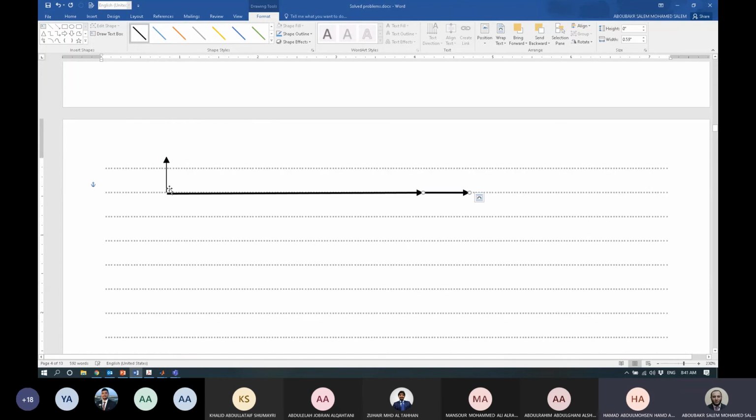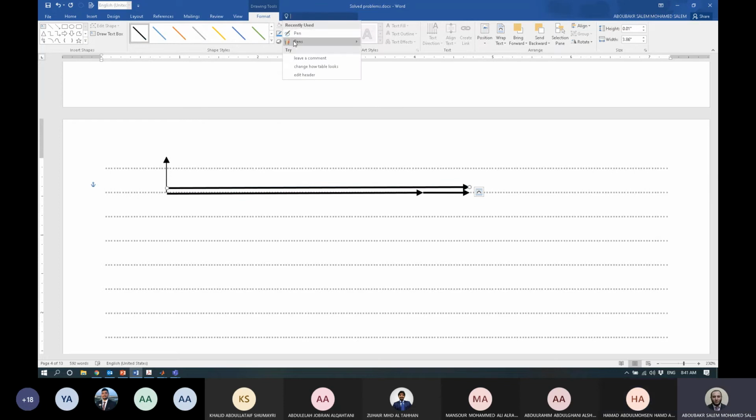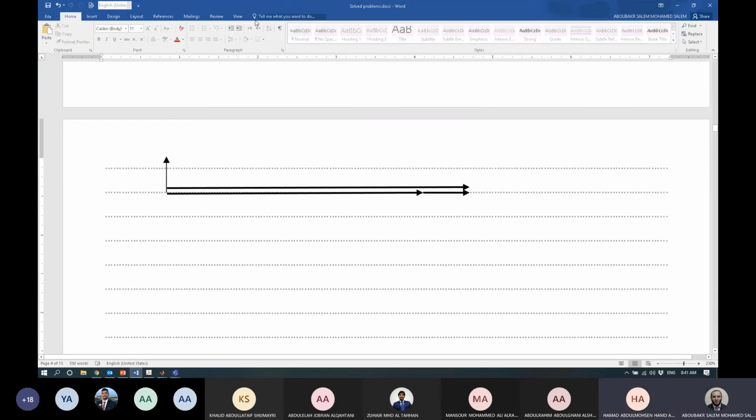And finally, EF should be the summation of these two vectors. So on the top here we can draw the vector of EF like that. So this is now the phasor diagram. This is V terminal, this is minus JIAXS, this is EF, and this is here IA. So this is the case of synchronous condenser type.